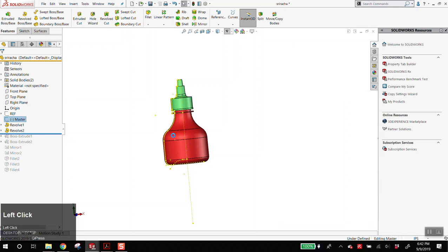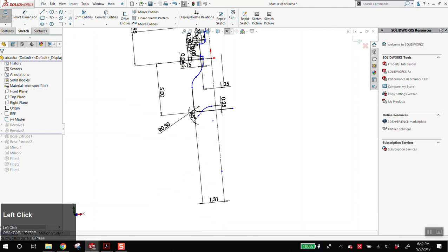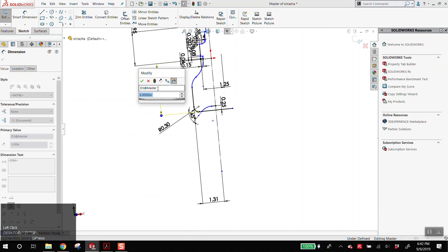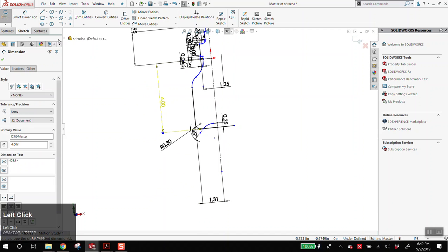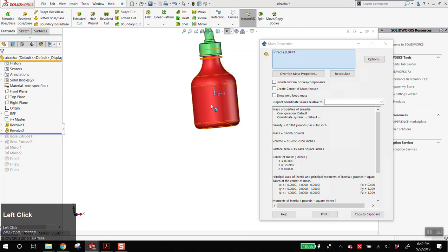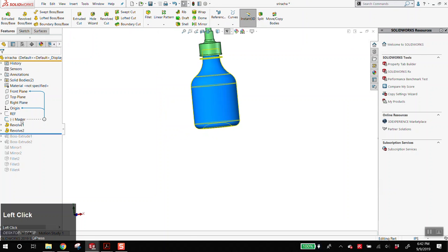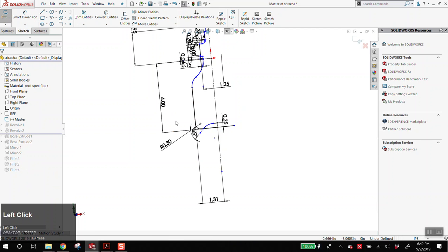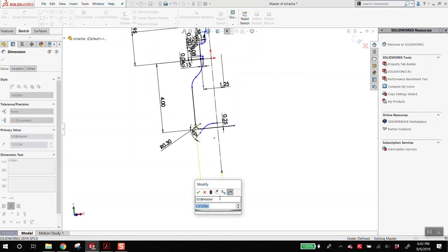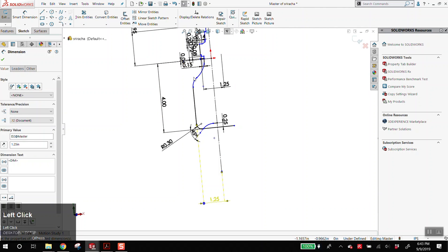So again, you would go back in here and you can edit whatever you want in the master sketch. You can change the overall width. So here, like if I went too little, it doesn't just have to be height. It's totally up to you. In general, you would probably go bigger and wider for the double size and shorter for the smaller size. Here's 17. So here, like the quickest way to reduce volume is changing the overall width or gain volume. So if I change this to like 1 1/4, and again, this is where all the dimensioning does become important.